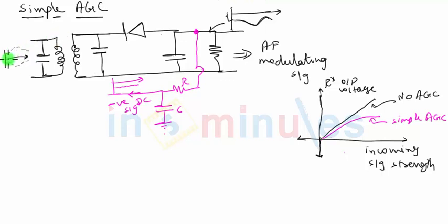The incoming signal which we have on the input of the receiver, and then on the input of the detector that we have just now taken, let's say is a double sideband full carrier signal. Now every DSB FC signal has some DC part available in it. It is the value by which the two envelopes have shifted away from each other. It also represents the carrier amplitude. We make sure that the carrier amplitude is very large on the transmitter side. As the signal travels through the channel, this amplitude reduces. So whatever negative DC we extract also tells us the amount by which the signal is attenuated when it travels through the channel and other systems before it reaches the detector.